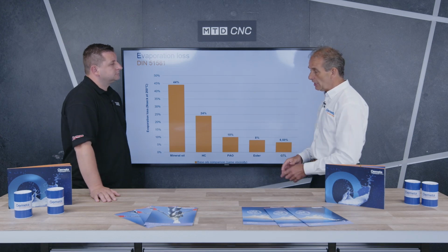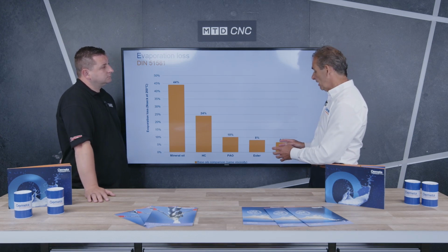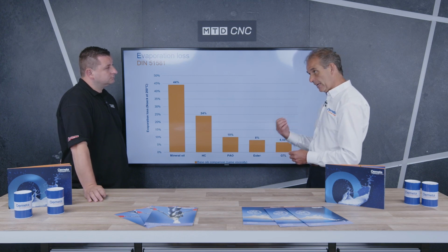I think another thing that we should look at is the health and safety side of things. So the ester technology is a really safe product to use. It's from a renewable resource. It's vegetable based, very pure, very high performance. But the advantage is with anybody using an oil below the viscosity of 20.5, so that's a lot of machining processes, sliding head machines, that type of thing. You would have to put, or there comes with the product, an exploding chest symbol on the drum, a hazardous label essentially. With anybody using ester oils, no matter what viscosity, there is no hazardous labelling.